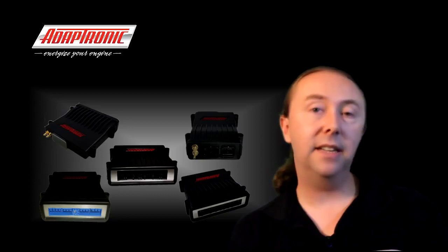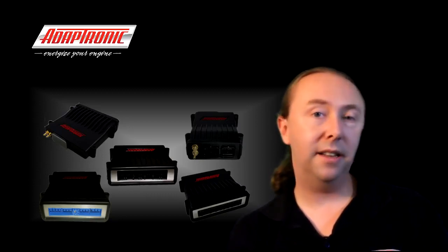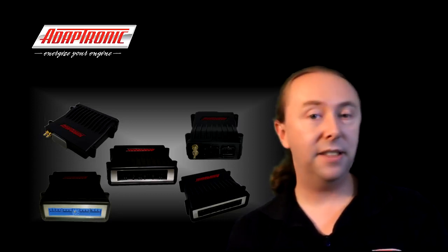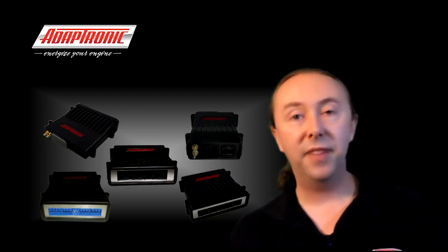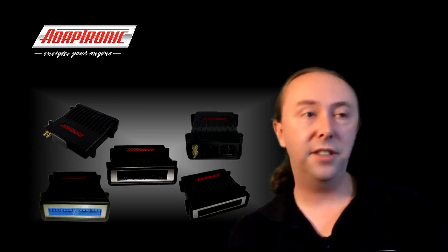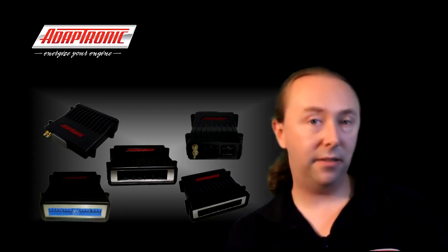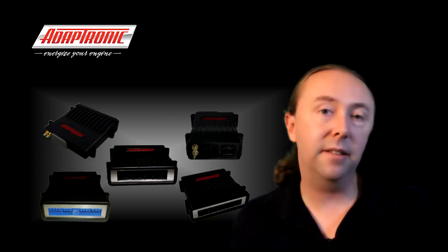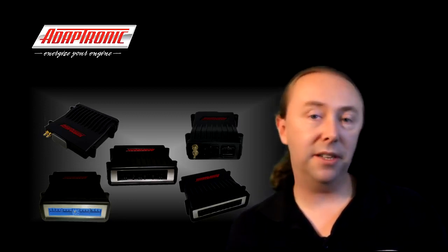A really easy way to do it is just to put a fuel pressure sensor on the engine, wire it into the ECU, and monitor. There's a variable in the main variables called differential fuel pressure. Monitor that. If it's a decent fuel pressure regulator, like a Turbosmart FPR 800 or 2000, that does not change all that much. And if it changes more than about 10 kPa or 1 psi, then you know that you've probably got a fuel system problem. And on several occasions where I've been helping set up ECUs for customers, make sure everything's set up right and that sort of thing, we get on the dyno and try and put a starting map into it and notice that the fuel pressure's all over the place.